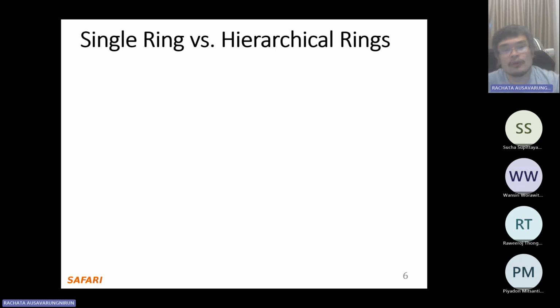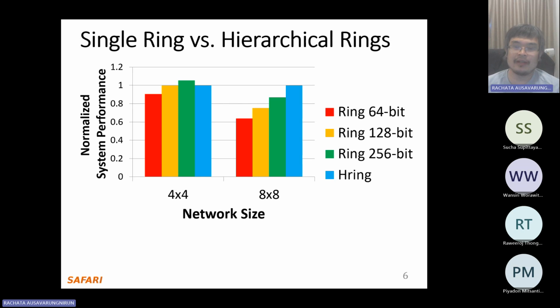All right. So let's evaluate some quick designs, right? If I look at performance on the y-axis here, you can see different bars show the scalability of the ring interconnects, but with different bisection bandwidth. Basically, at each of these points I make the link wider, so more things can be transferred through the link.